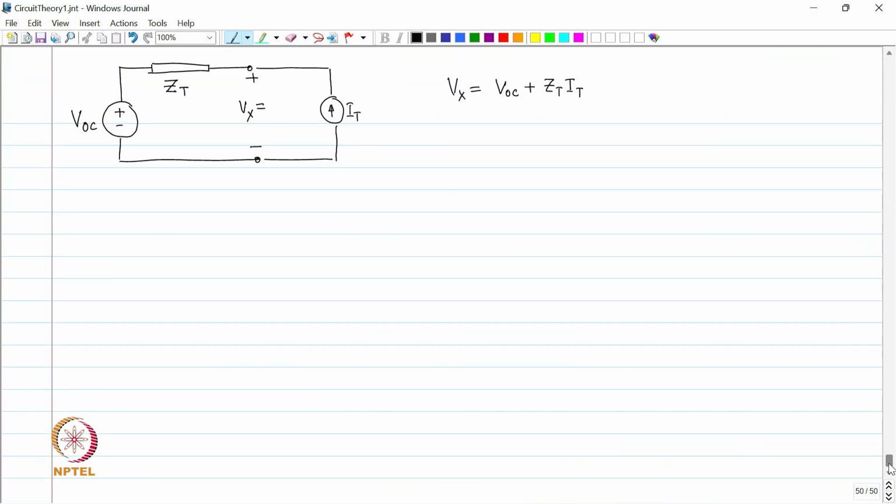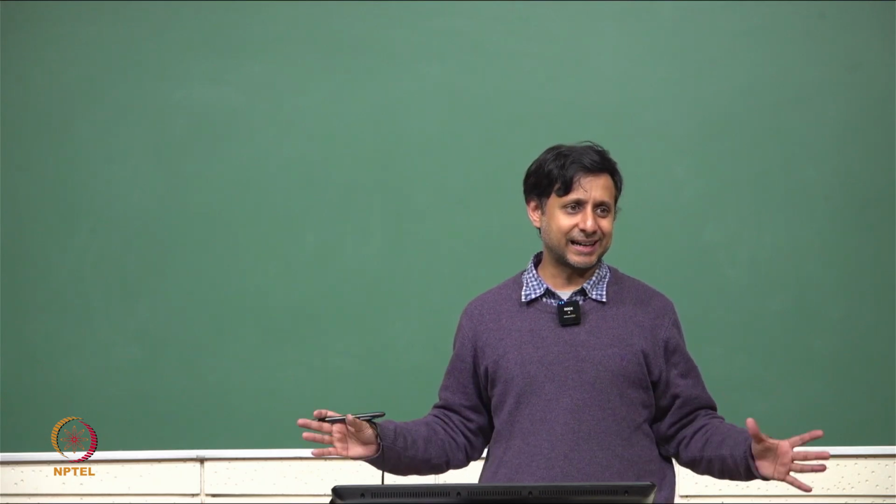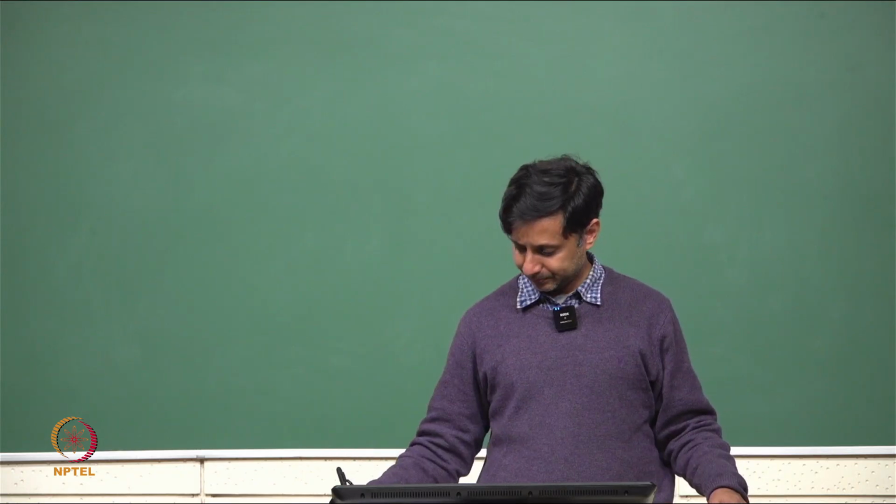So, I mean this is basically the theorem, right. Norton's theorem you can prove exactly in the same fashion, but for Norton's theorem you have to apply a voltage source, do not apply a current source first of all, and then use mesh method, do not use the node method, because when you work with voltage sources mesh method plays better just for that reason. So, use mesh method, apply a voltage source outside, and with Norton's theorem you will get exactly the same, it is exactly the same procedure, the dual procedure. Fine.